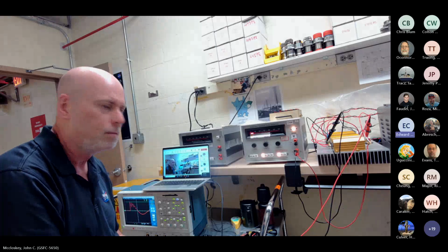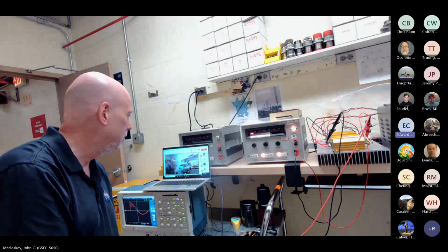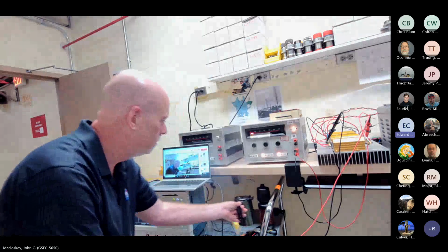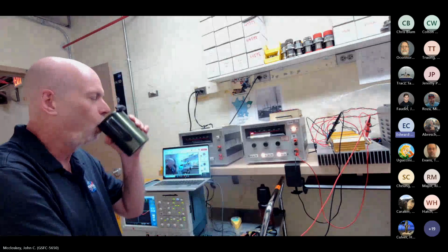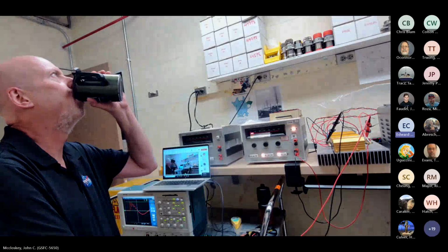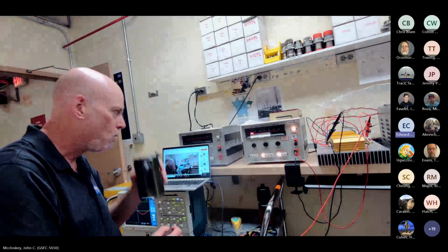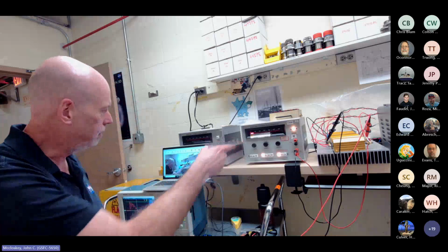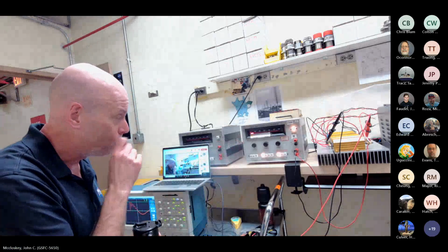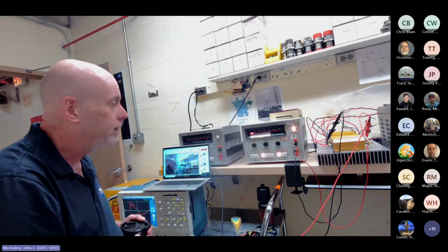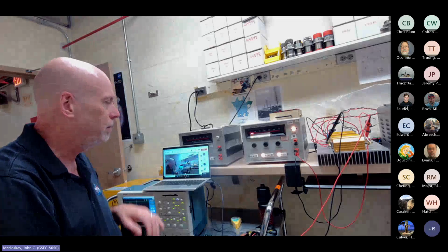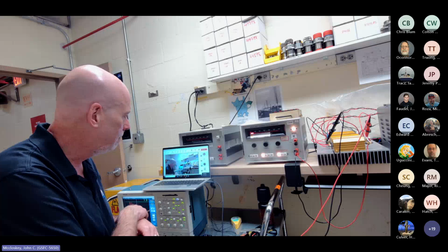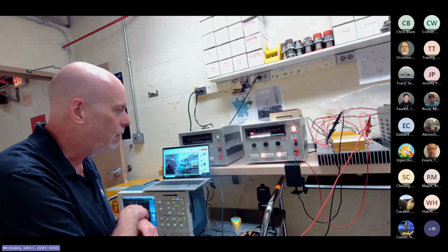I have another comment, I guess, John. This is Ed again, by the way. I think possibly James should measure the inductance of those resistors, so we know when we are at 45 degrees, since you're not sure. The load resistors. Yeah. It'd be interesting to put those on an impedance analyzer to see how inductive they clearly are.